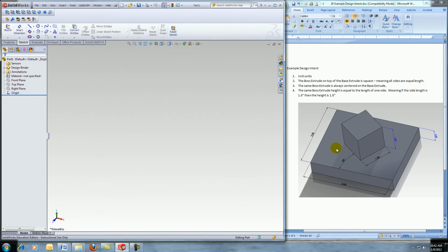As I look at this drawing, I want to decide what I want the top view and the front view to look like. So if I were looking down this direction, and this is a view looking down would be my, let's say, front view, then over here I probably would just have to decide which one is my plane that I might want to start out with. And if you build it in a different plane, you can always rearrange it in drafting, but in this case I'm going to use the front plane to represent what I want to be the front view.